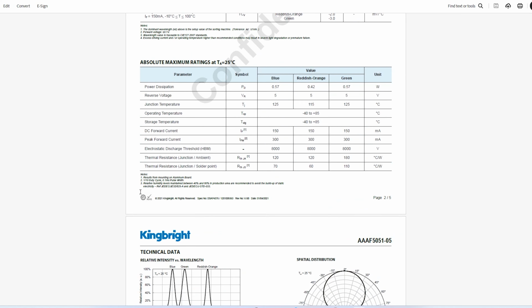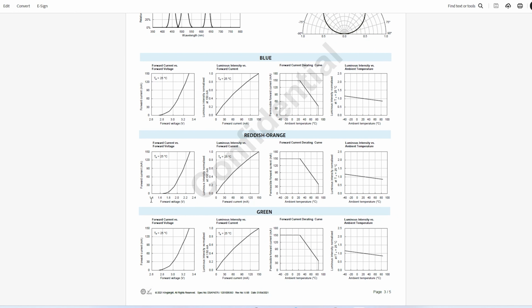And if we come down here, we're looking for the data on the forward voltage of the LED. So this specific graph is an indication of the blue LED's forward voltage. So we see right here that not until we reach 2.7 volts do we start to see an increase in current. So the current is not increasing linearly. We see this current changes as voltage is applied to it. So that's in direct reference to the resistance. So the resistance is going down as we increase in voltage, and so we see that current flowing.